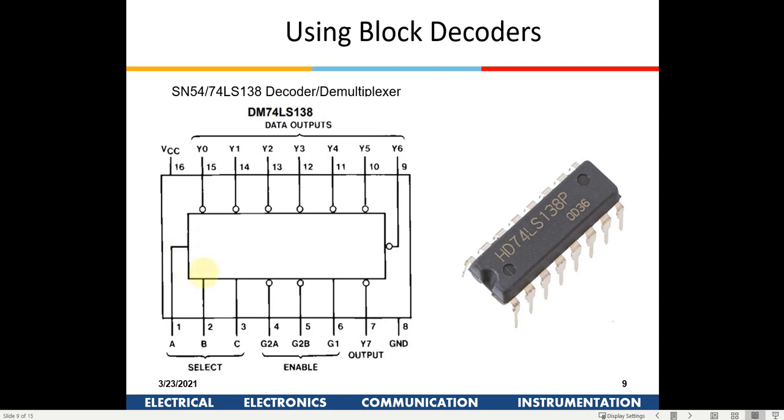A is also here. Pin number 1 is available here, right? And when you see an IC, there will be a notch out here. When you look from the top, this notch is to be kept on the left hand side. So the pin starts here with 1. This is how you identify a chip. So 1, 2, 3, 4, 5, 6, 7, 8, 9.